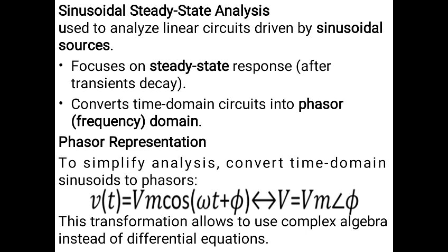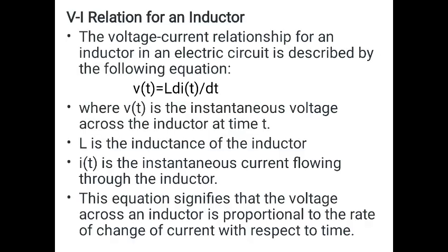Phasor representation. To simplify the analysis, we can convert the time domain sinusoids to phasor or frequency domain, where v(t) = Vm cos(ωt + φ) is written as Vm ∠φ. This transformation allows us to use complex algebra instead of differential equations.